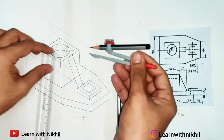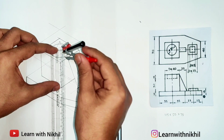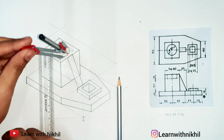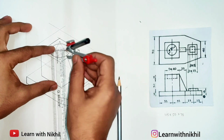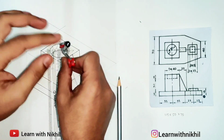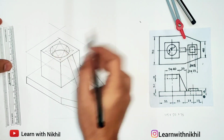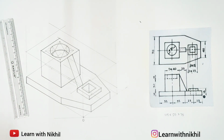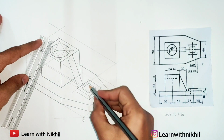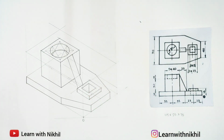So only this part will be there. Again shifting this point 10 millimeter below and then draw the curve. So this is how you have to draw the curves by shifting the points. As the circle is drilled at a height of 10 millimeter, we have to do this. If it was totally drilled till the bottom, it was not necessary. So the square, the edges we have drawn.